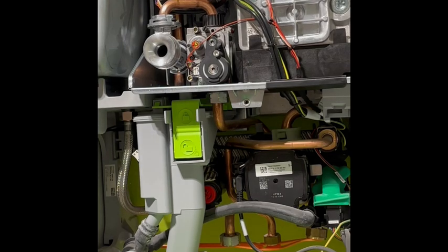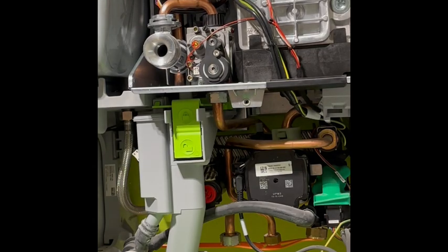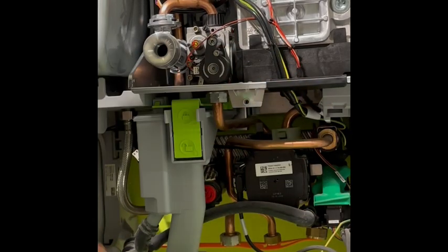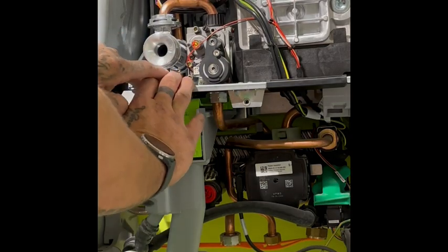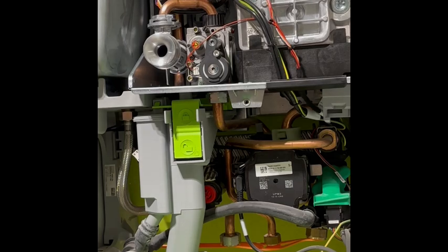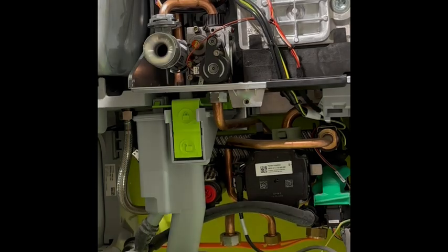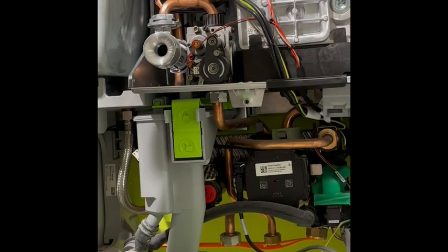Okay, so it's important to remember when you're starting a breakdown, or when you're looking at repairs on boilers, always start at the start of the process. A lot of people just lose their way and they jump in halfway through the process and miss some of the start of it. So, for example, we're going to look at an ignition fault. First thing you want to do is ask the customer what's going on. Ask them some questions. If there's a pattern to it, is it just straight ignition fault all the time?